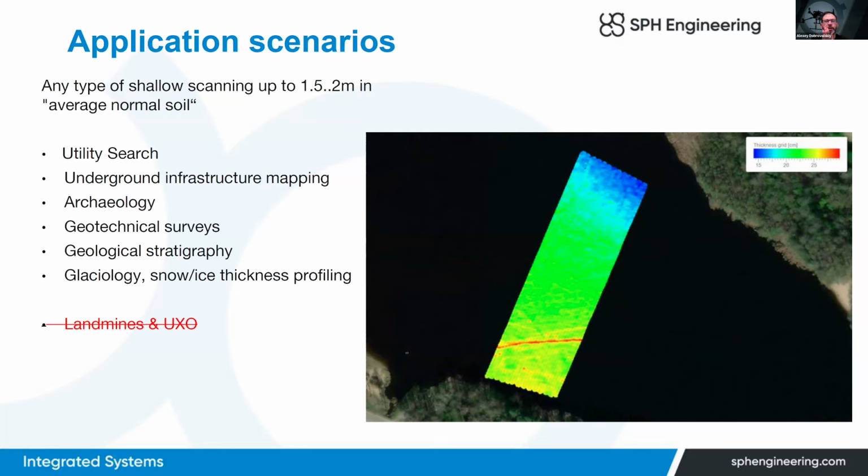They can be used for archaeology, but very important not to detect small artifacts, mostly to detect something big like hidden basements of the buildings, or just to profile strata or soil layers before excavation. For shallow, they can be used for geotechnical survey.